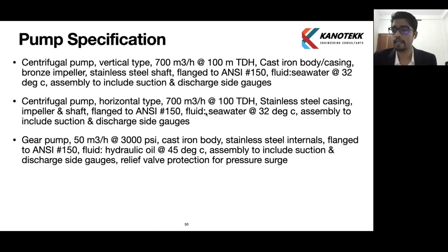Relief valve protection. So this is a requirement for all positive displacement pumps. They require a relief valve because, compared to a centrifugal pump, positive displacement pumps like gear pumps, lobe pumps, etc. continuously build up pressure in the system. So we need to have a relief valve to protect the system from crossing the design limits of the pressure value. So this is about pumps actually.